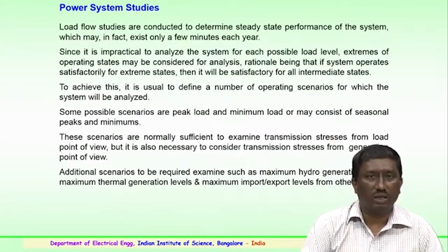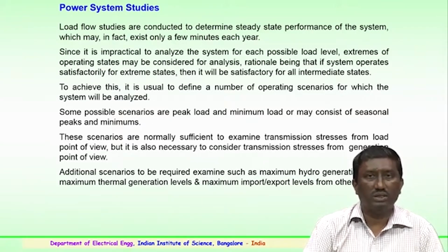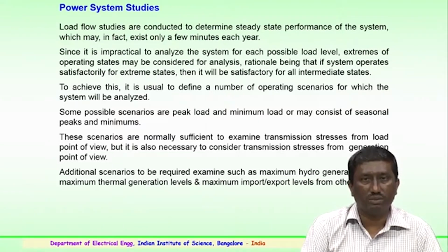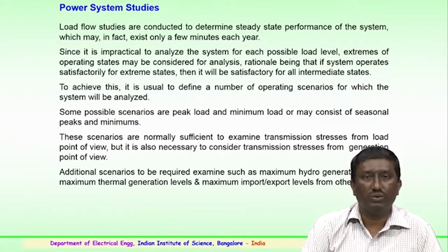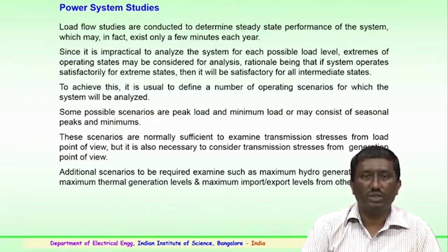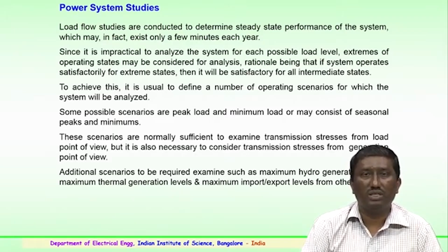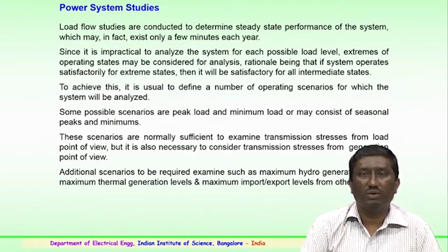So, various studies are being done, like transmission related studies. For the substation also you have to have prior knowledge of the conditions of that area and the voltage level where the substation is planned. Power system studies, the important being load flow studies, are usually conducted to determine the steady state performance of a system, which may in fact exist only for a few minutes in a year. This is very important, since it is impractical to analyze the system for each possible load level. So, extremes of operating states may be considered for analysis.